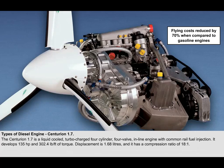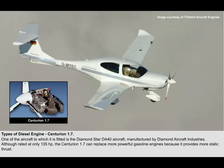The Centurion 1.7 is a liquid-cooled, turbocharged, 4-cylinder, 4-valve inline engine with common rail fuel injection. It develops 135 horsepower and 302.4 pounds-foot of torque. Displacement is 1.68 litres, and it has a compression ratio of 18:1. One of the aircraft to which it's fitted is the Diamond Star DA-40 aircraft, manufactured by Diamond Aircraft Industries.